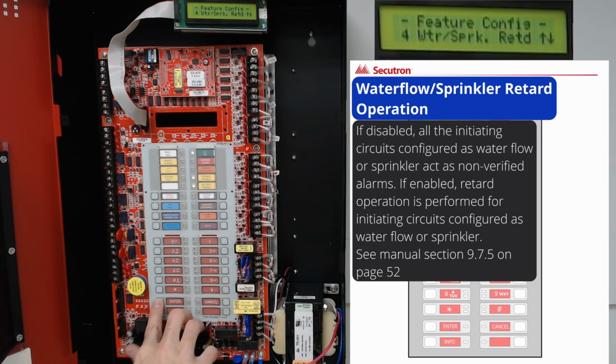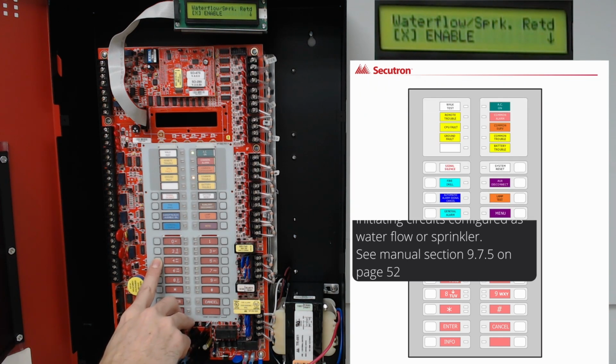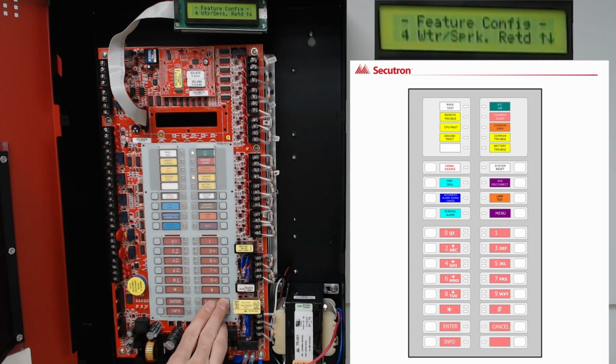Our next option under Feature Config is Water Flow Sprinkler Retard Timer. By pressing Enter, we'll enter into its options. By default, it has been selected as disabled. If we press the up cursor arrow and then the left or right cursor arrow, we can then enable our Water Flow Sprinkler Retard Timer. Press Enter if the enable selection is what you choose, and then Cancel to exit back out to the previous menu screen.